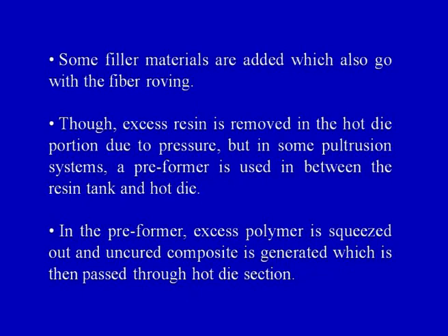So, the complete process can be explained with the help of a diagram also. But before we go to the diagram, there are a few other important points that we need to discuss, that is, some filler materials are added which also go with the fiber roving. So, filler materials can be added in the resin bath also, they can also be incorporated